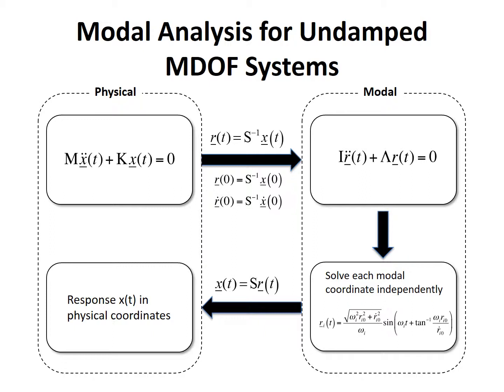So in summary, we have shown that the solution to the free vibration problem for multi-degree of freedom systems can be related directly to the solution of an eigenvalue problem of a real symmetric matrix. The orthogonality of the eigenvectors and their ability to diagonalize the equations of motion result in an efficient method of solving the coupled ordinary differential equations that represent multi-degree of freedom vibrating systems. In this chart, we describe this approach.